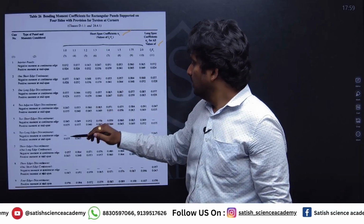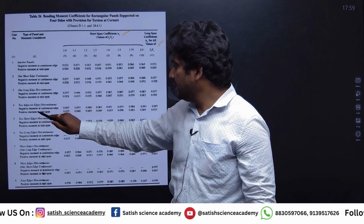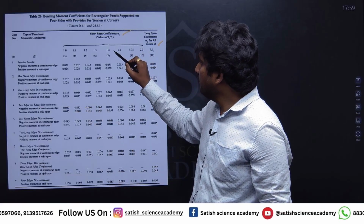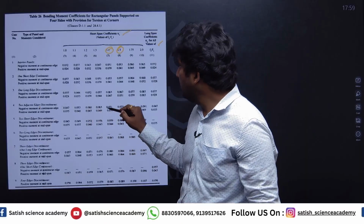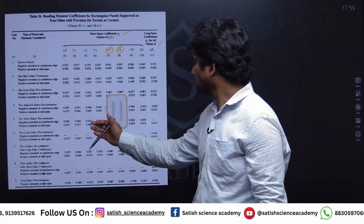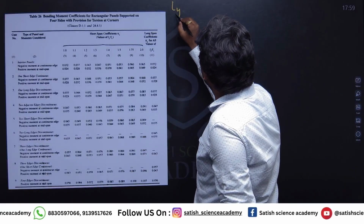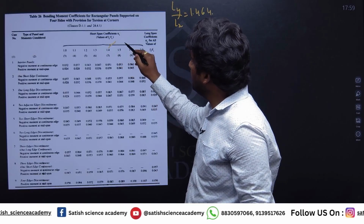long span moment. Our condition is two edges discontinuous: negative moment at continuous edge and positive moment at mid span. Like this, they will be having two adjacent edges discontinuous. So our coefficient values are 1.4 and 1.5, and our value is lying between these two. So Ly by Lx ratio, we got it as 1.464, that is lying between 1.4 and 1.5.